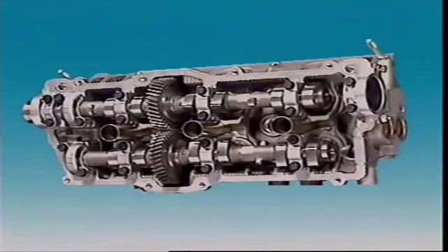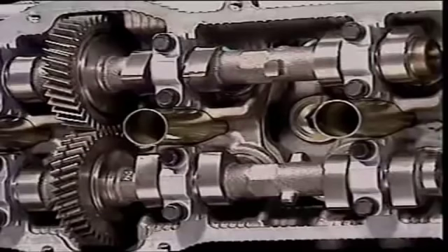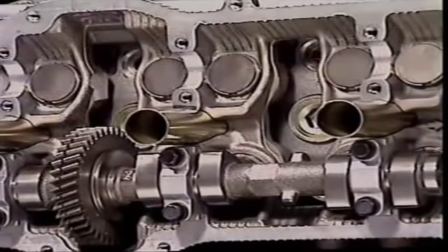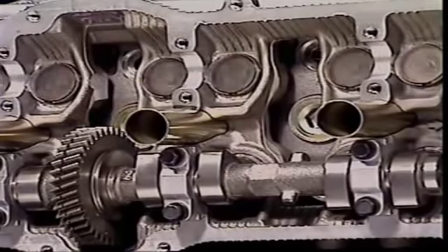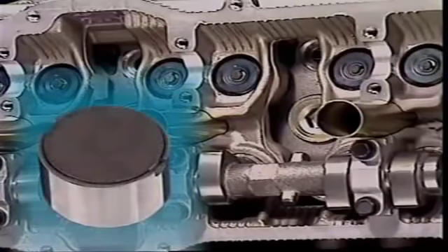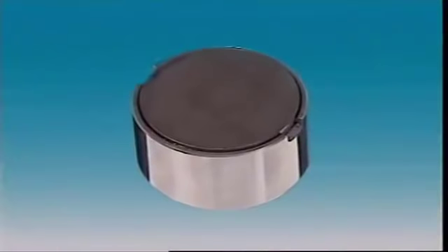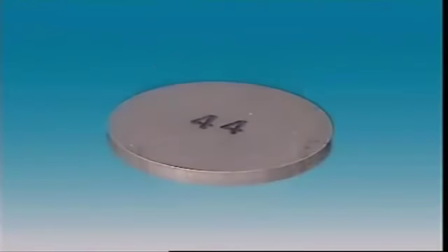On double overhead camshaft systems, the most common arrangement is to use a bucket tappet or lifter. It operates in a guide that protects the valve against side thrusts, which it would receive if the cam operated directly against the valve. The adjustment of valve clearance is usually done by changing accurately machined spacers. Spacers are available in a range of thicknesses, and they're exchanged to obtain the correct clearance.